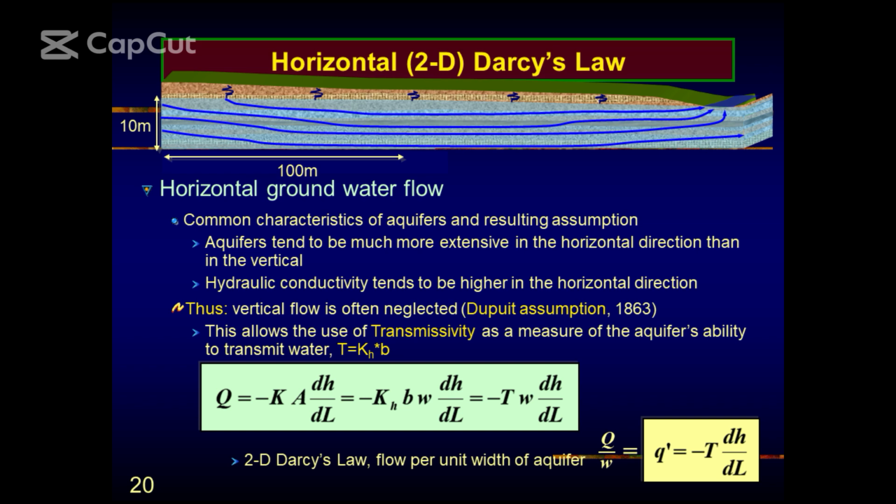And yesterday, I took a lot of time to explain why it is not a vector, why the flux is a vector and the discharge is not. The same thing, because it refers to a particular area that is perpendicular to the flow path. The same thing with the discharge per unit width or the flux per unit width. The width we are referring to is any line segment across the path of flow, which is perpendicular to the flow path.